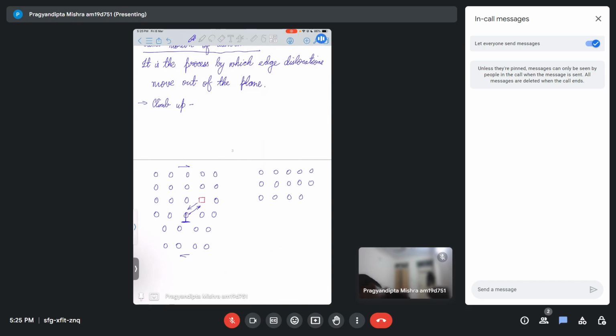Now the third layer is perfectly filled because the vacancy and atom exchanged. But from the fourth layer onwards, now we have only 4 atoms. Earlier, from the fifth layer onwards, there were 4 atoms. But now the dislocation has moved one layer up. Right? So now the dislocation has moved to the fourth layer. So we can say the dislocation has climbed up. It has moved up by one layer, while the vacancy has moved in. Or the dislocation is now acting as a vacancy sink.